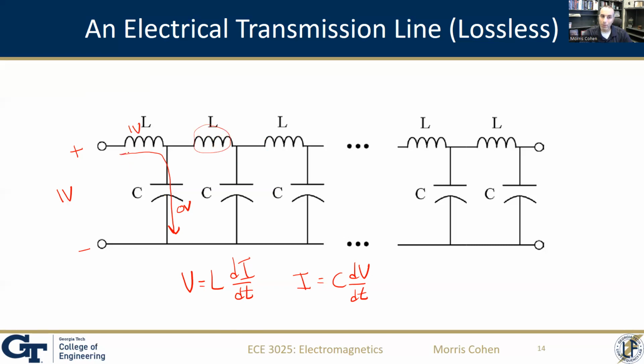So in that first moment, it's going to start to charge up this capacitor. So a little bit of current is now starting to flow through the capacitor. As that current flows, the capacitor charges up and it starts to build up a little bit of voltage. And so wait a little bit, we maybe get 0.1 volts on the capacitor and we'll get 0.9 volts on the inductor. So we're starting to flip the order of all of this.